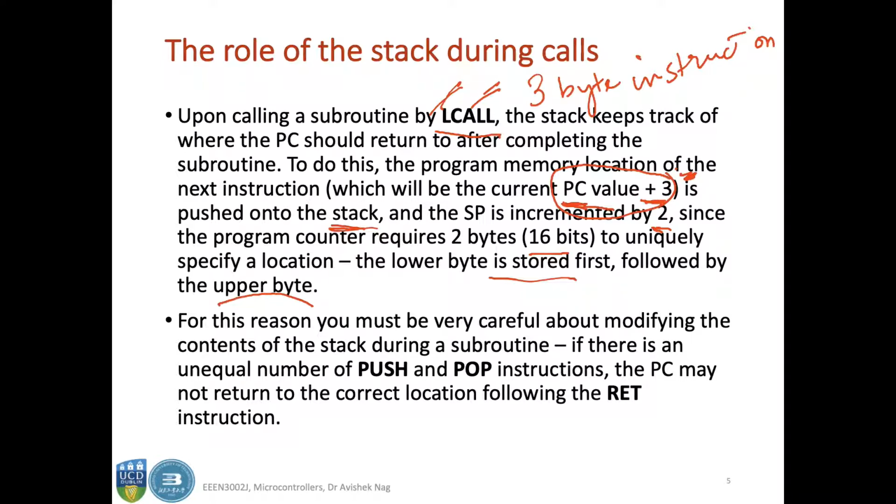So you are using the ACALL instruction. ACALL is a 2-byte instruction. First of all, the program counter, which is located at this line at the beginning of the ACALL instruction, will contain this number, 0026. Now after the ACALL instruction is executed, since it is a 2-byte instruction, the program counter will now be program counter plus 2. So that is this number.